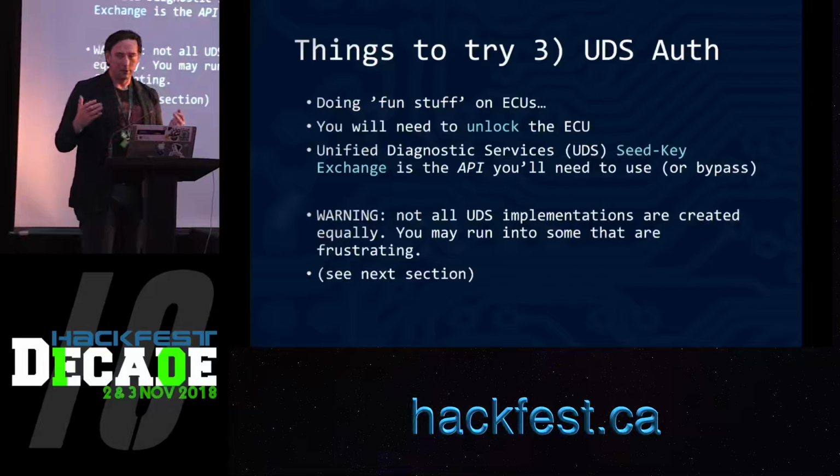Remember, you can install your CAN bus sniffer and then bring your car to the garage, and you will see the seed key exchanges from the tool, right? So 10 is a totally reasonable number for this. And then of course you can glitch past.